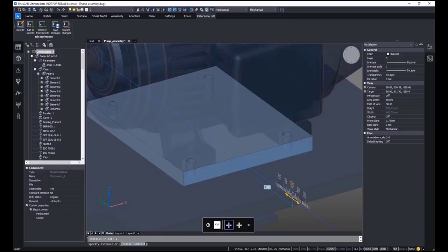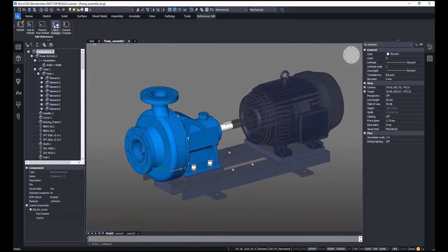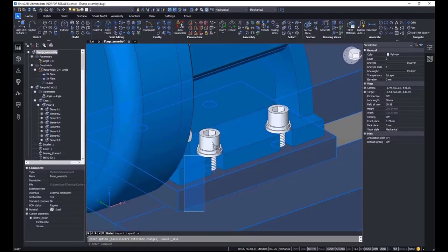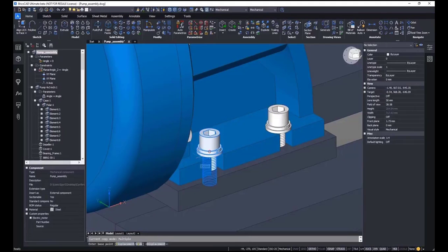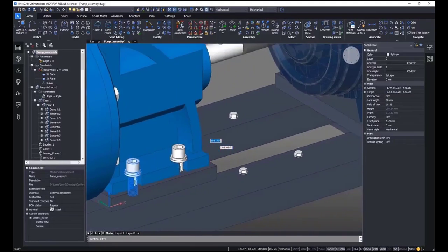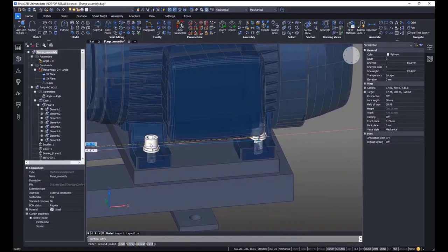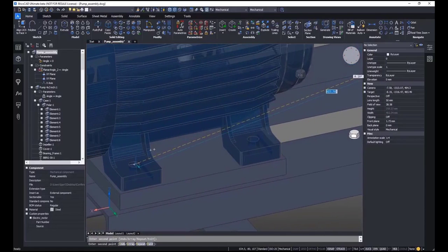By closing the refedit session, we update the external DWG file that represents the plate subassembly. Now we can insert the fastener into mounting holes. We are doing that by copying existing bolts with snapping to the center of circular edges. And that's it. You can see that assembly editing with imported parts can be done much faster in BricsCAD Mechanical version 22.